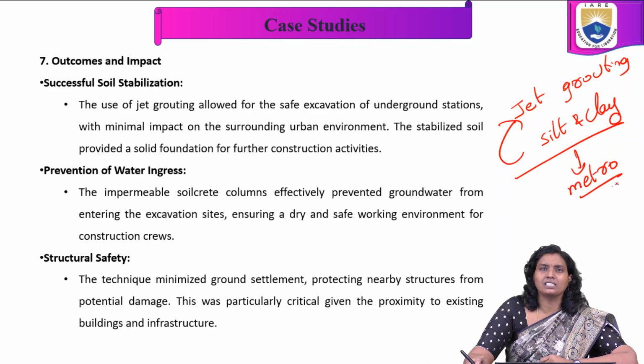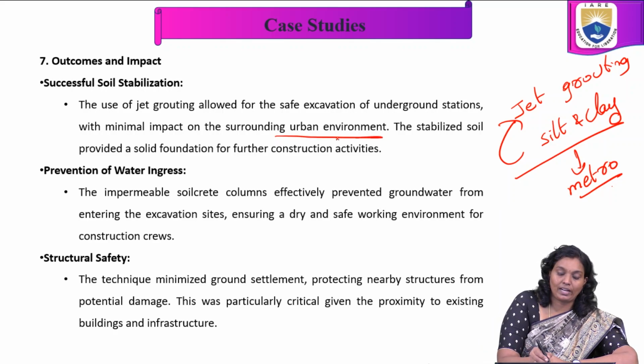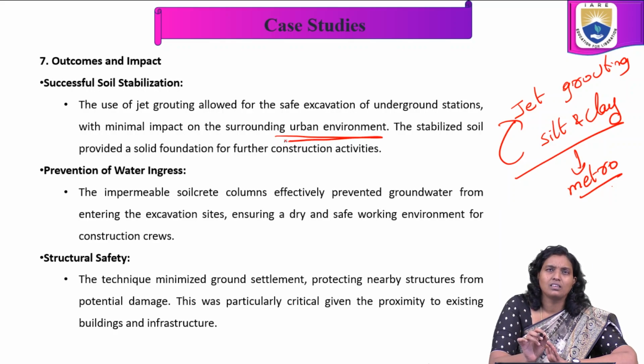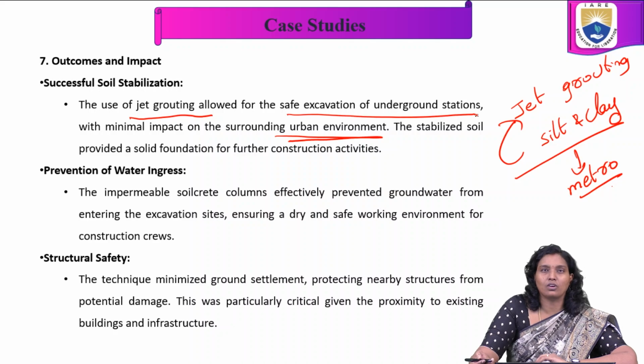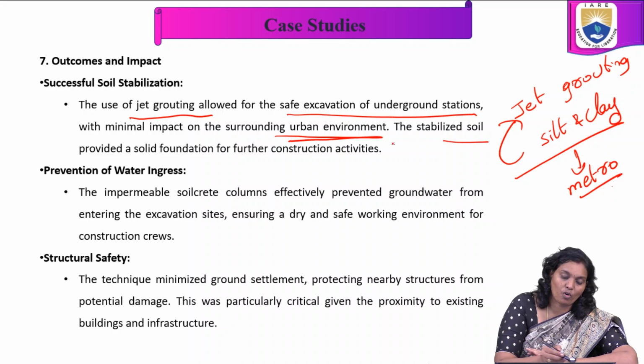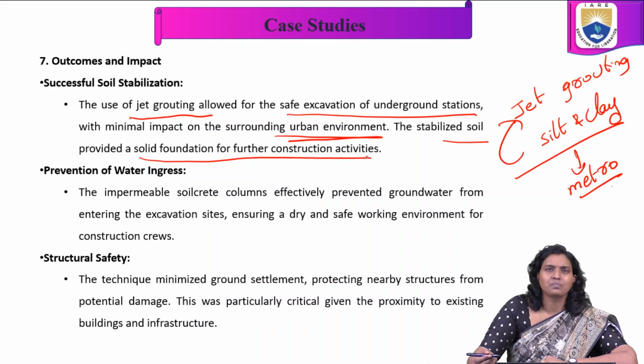Here, the successful soil stabilization. The use of jet grouting allowed for the safe excavation of underground stations with minimal impact on the surrounding urban environment. This is one of the important success points for this outcome. We used jet grouting, which allowed safe excavation of underground stations with minimal impact on the surroundings because of the urban setting. The stabilized soil provided a solid foundation for further construction activities.